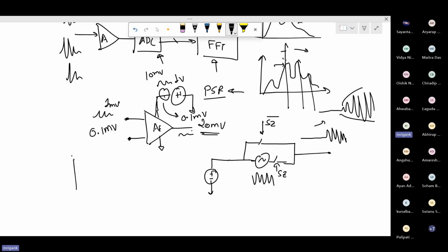If you have a differential amplifier and you have a bias current for this, as you increase the bias current, the gain generally drops. So now you have the active low differential amplifier, and your sinusoid signal is coming here. The only problem is how will you combine. Even if you change the current, a ramp current, is it available?